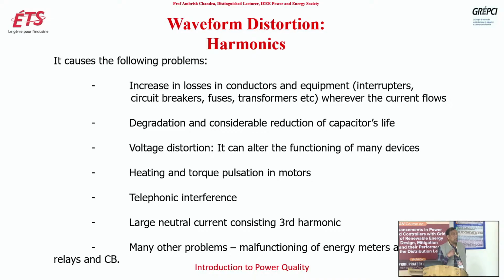So this is very important to know why there is heating, and heating is there because you are having harmonics, and the fifth harmonic, 7th, 11th, 13th, 17th, 19th, those harmonics are there, and then they will generate extra losses in the core, in the rotor and stator material because of the ferromagnetic losses, hysteresis losses, and the eddy current losses.